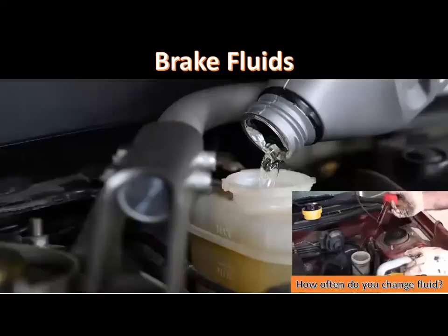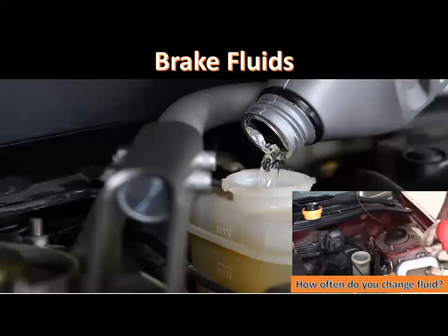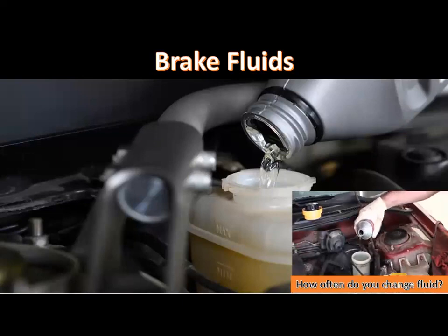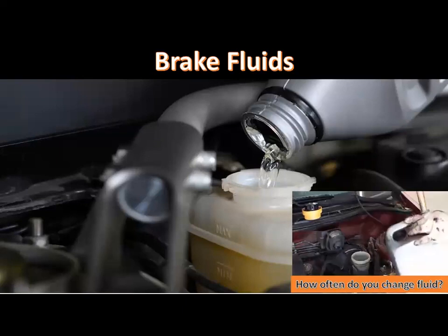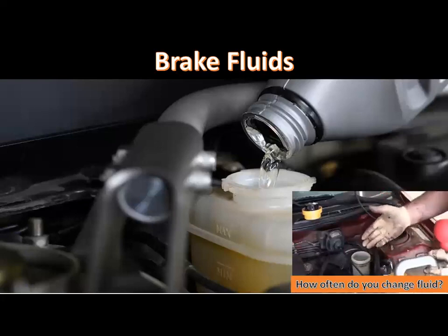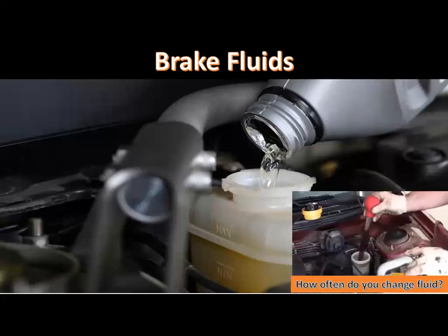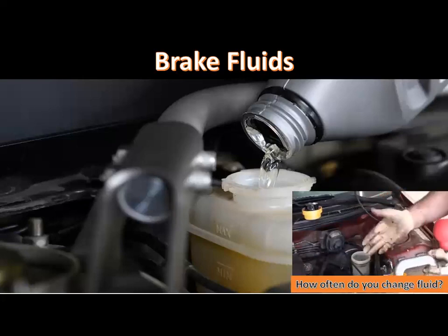Brake fluid quality is extremely important to provide proper brake system operation. Brake fluid must have these qualities. Brake fluids must provide a controlled amount of swell in cups and seals to provide adequate sealing in calipers, wheel cylinders, and master cylinders. Excessive swelling of cups and seals causes brake drag and inadequate brake response.